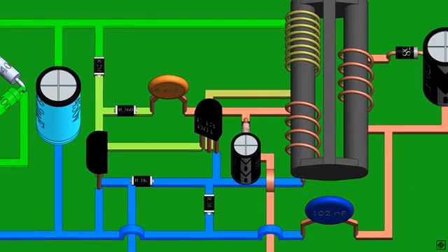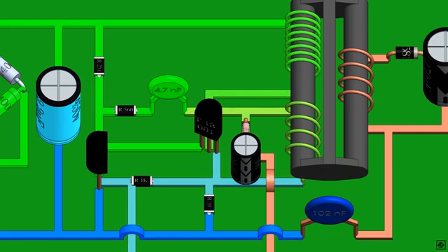Now, this current passes from the 2 megaohm resistor to the base of T1, turning it on. This transistor isn't fully turned on because of the resistance, it turns on partially. Due to partial turning on of the transistor, a low current passes through the primary winding of the transformer. This induces a low voltage in the auxiliary winding. The induced voltage now charges the capacitor, and then the capacitor fully turns on the transistor. As the transistor is now fully on, it allows the current to flow through itself. Now, this turns on the transistor T2.